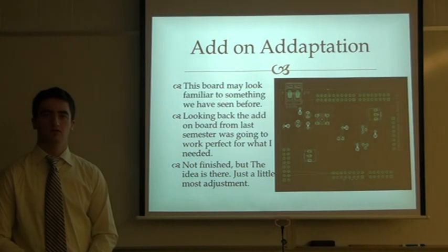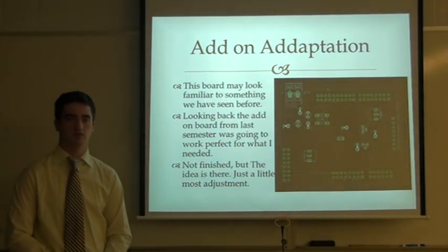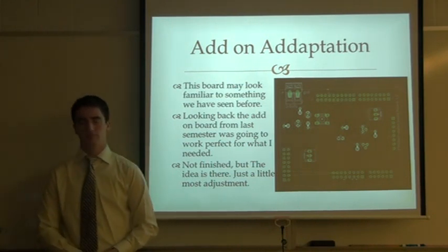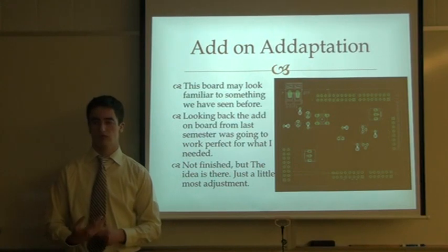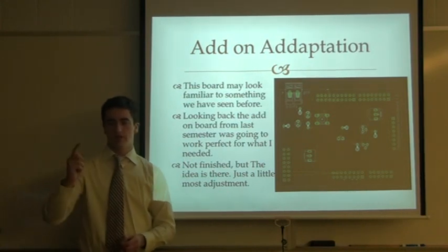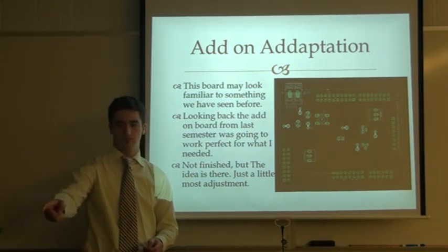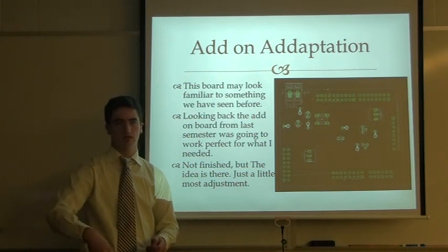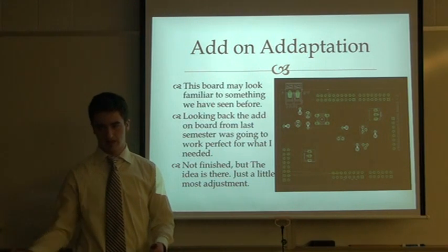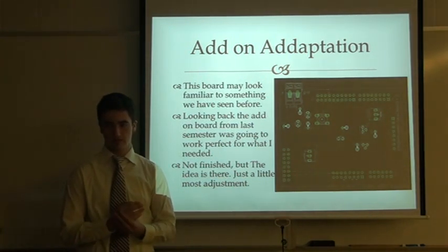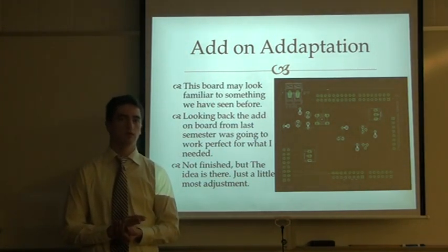You were talking about the voltage regulator. It's not on the board, right? Right. Yeah, I just have to put in a 3-pin, or 3-terminal, device, and then assign the pins for it to basically pick up from the V in, tie the excess to ground, and then the outward pin will tie into the power for the board.